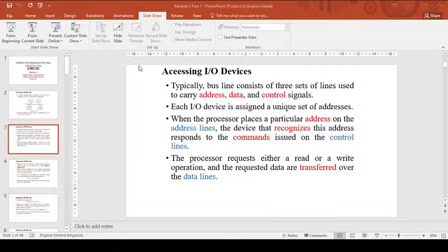So here the operation is to move the content of the register data in from the input device to R0. This is an IO read operation. It reads the data from data in and stores it into processor register R0. This is the example for reading the input device in memory mapped IO. And for writing, move R0 comma data out.